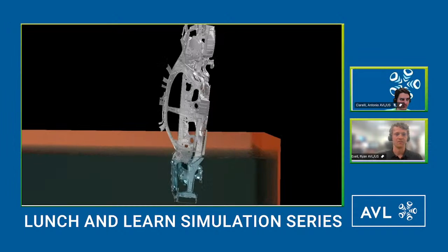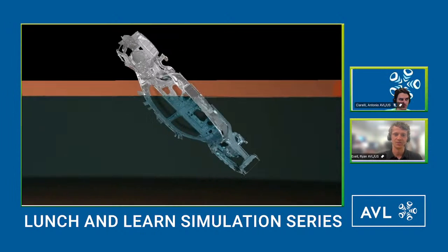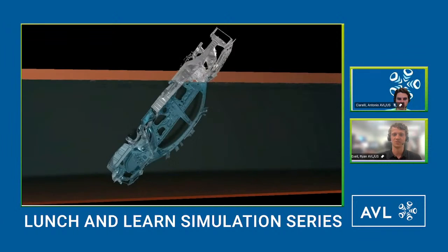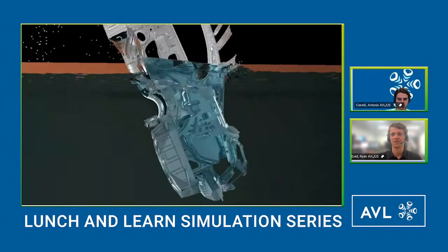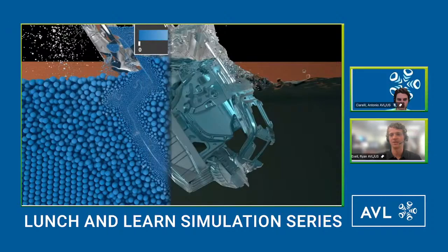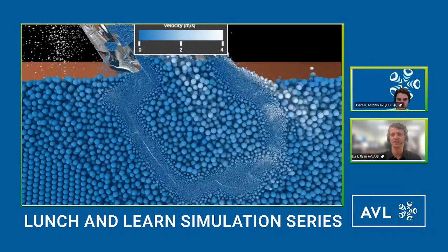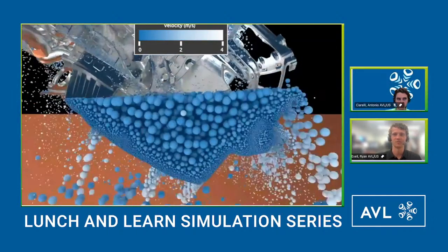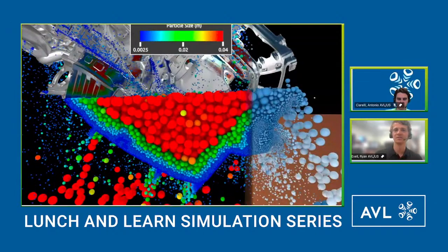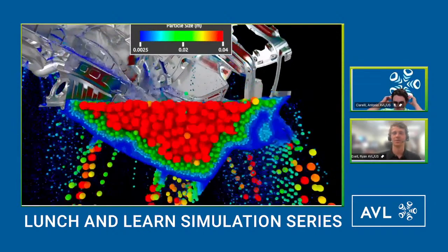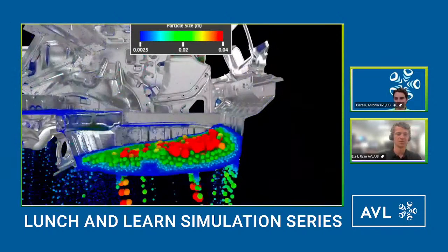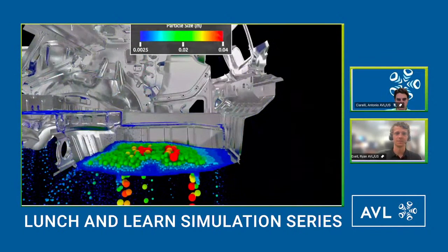Here we have a video of a dip coat application that has utilized CPS to ensure quick simulation times. The continuous particle refinement here is controlled using a set proximity to the part's surface. And you can kind of see that here with this visualization. And then now we're looking at the particle sizes with each color.